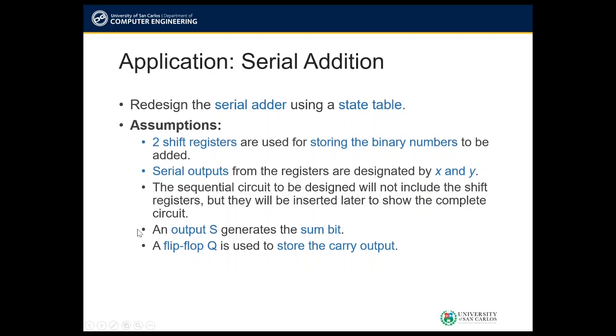An output S generates the sum bit, and a flip-flop Q is used to store the carry output. And the carry output, which is stored in the flip-flop, would be used as the third bit to be added together with X and Y.